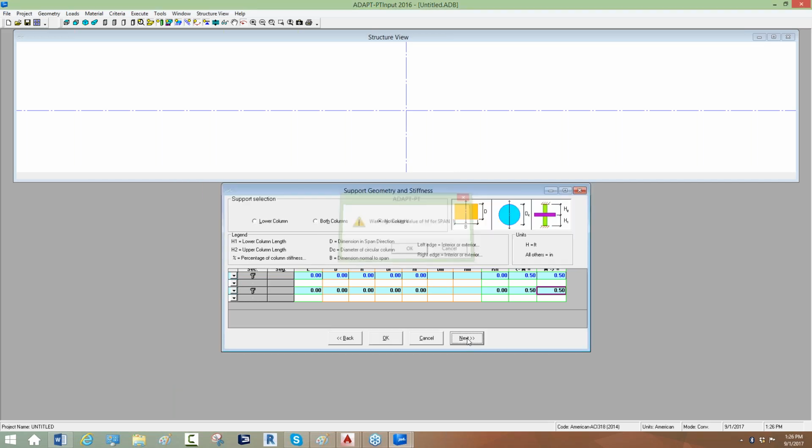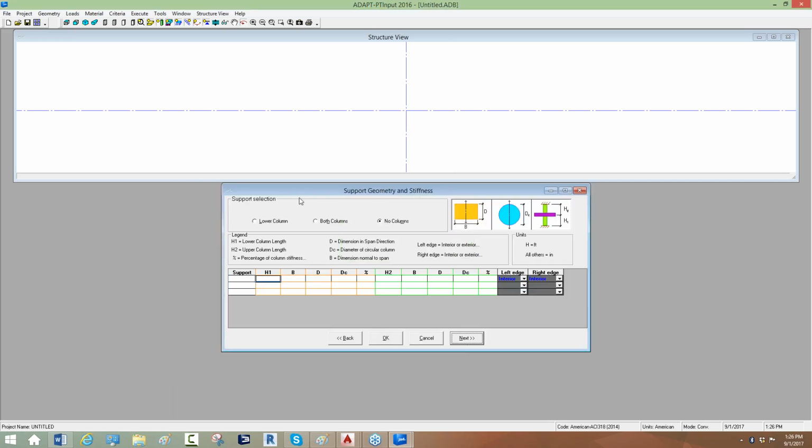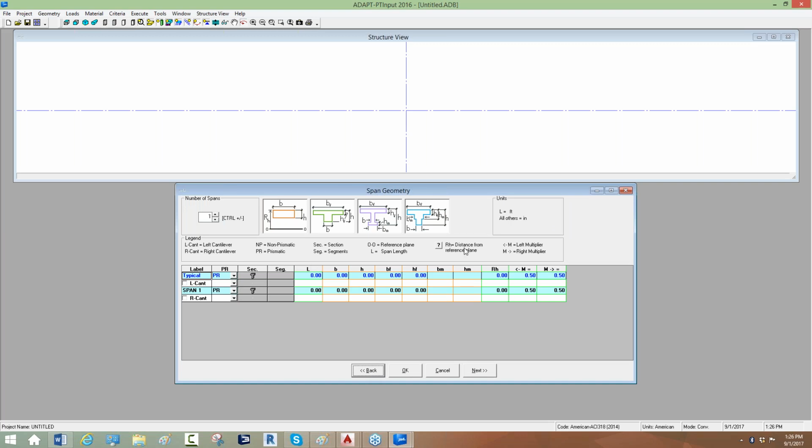And you can see, I'm just going to cycle through this. You can see this actually bypasses the effective width window. So if you wanted to use effective width for an extended T or an I section or L section, whatever you're using, you basically have to model that as part of the geometry for the main span geometry.